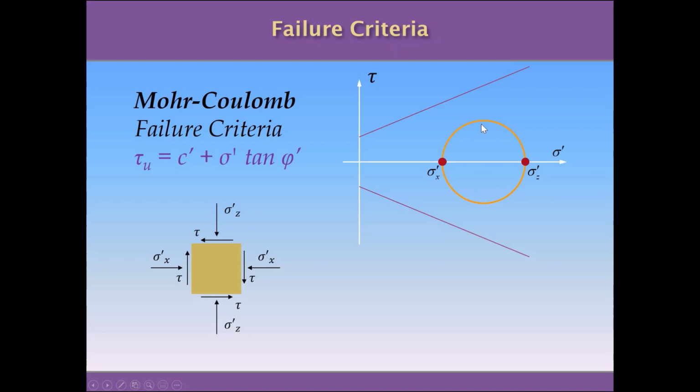So the bigger the Mohr circle, the closer we are to the failure. If you reduce more the value of the sigma x, for example, and we touch with the Mohr circle these two lines that define our limits in terms of failure criteria, we are going to reach a state of stresses that make the soil fail in this theory. So we are going to have at this point a pair of axial stresses and shear stresses that will produce a failure in our soil.